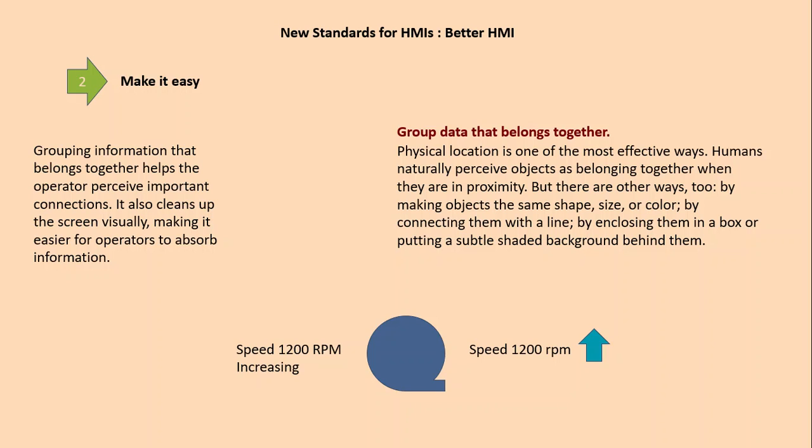Parts of the plant that are related to one another can be shown in a grouped format, where the background color is the same, and on top of the background you display those small instruments and components together in that area, to group them together. That way the operator will understand the situation of that particular group of machines.